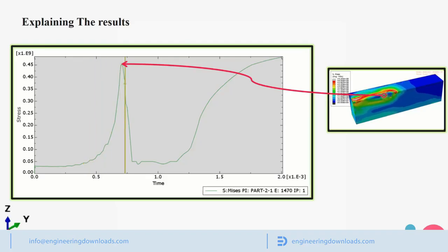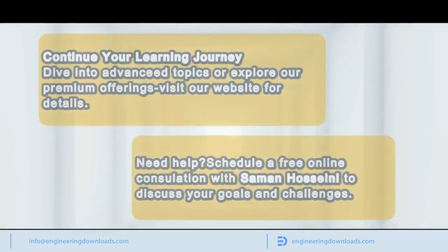For residual stress, we can explain that it is generally created when the material undergoes manufacturing processes, such as extrusion, bending, and rolling, that change its shape. Residual stress can be both advantageous and disadvantageous. For instance, if it creates tensile stress in the material, it will reduce the fatigue life. If you are interested in predicting the fatigue life with FE-Safe software, please refer to the link I have put here.